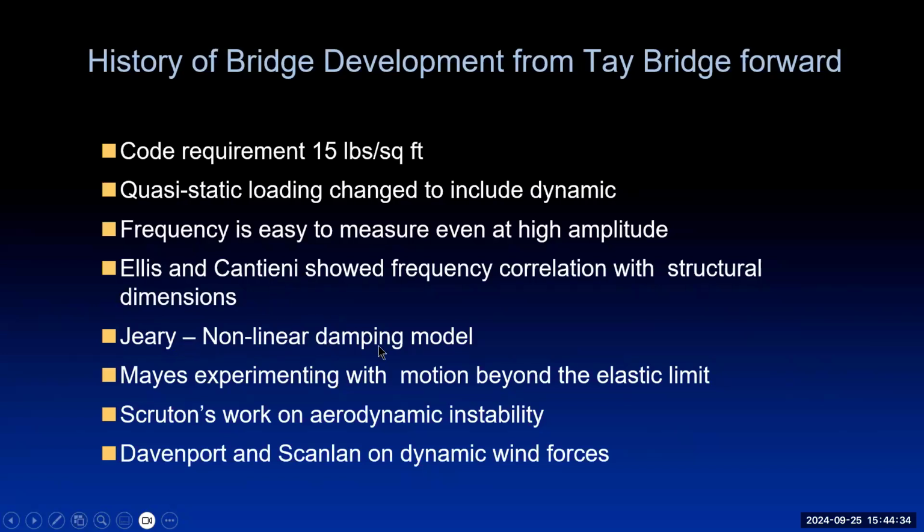The most difficult thing was damping because it's nonlinear. Seismic engineers really wanted to know, but they said, you cannot do it. It's too complicated. Well, in the 1980s, I introduced something based on what NASA had done to look at the nonlinear response of nonlinear damping characteristics of a building. And as a result, it was able to put together the frequency expectation and the damping expectation. And by that, we can actually look at the displacement per unit force. We can do that in the linear elastic zone, but it's useful. And I'll show you in a moment exactly why.